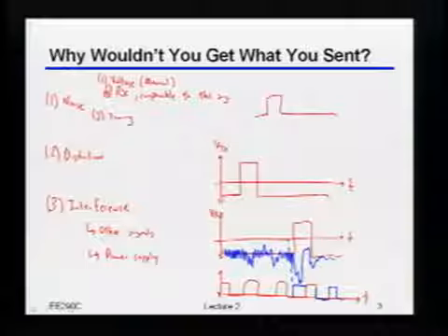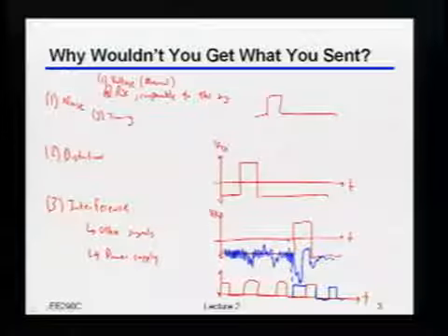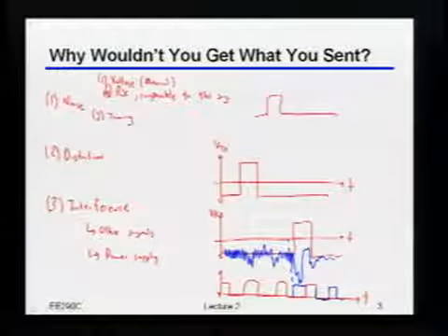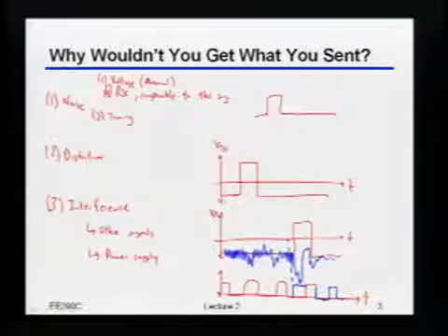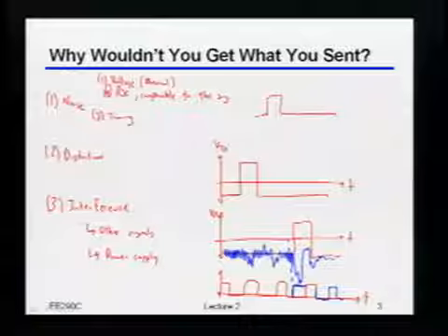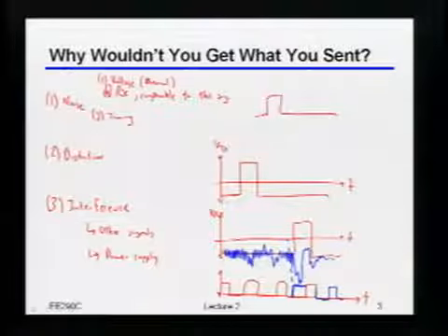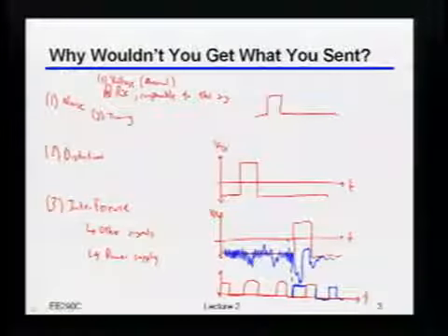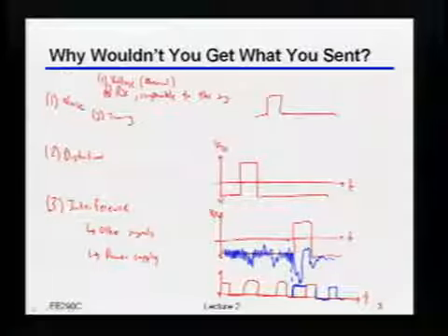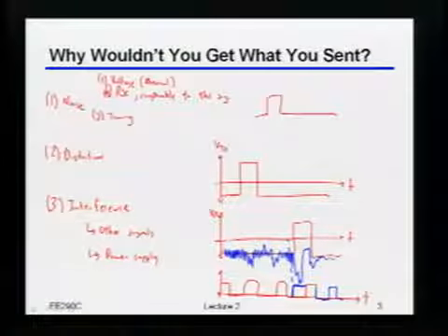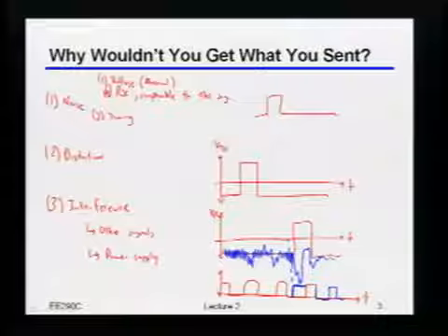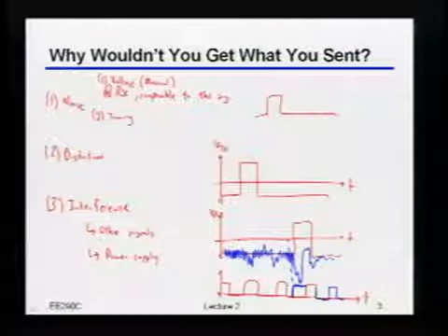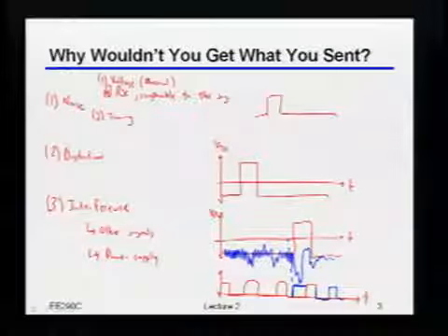So to state what you're saying in another way, any of my timing signals are fundamentally a voltage, right? So if I put noise on that voltage, then fundamentally there's uncertainty in time as well, right? Because the only way I can tell what time it is is based on some voltage signal, okay? So it's really kind of the same thing. It's just that timing sometimes tends to be a little bit more confusing, because the way it ends up causing errors is a slightly different mechanism than just voltage noise pushing you in voltage into the wrong place, okay?